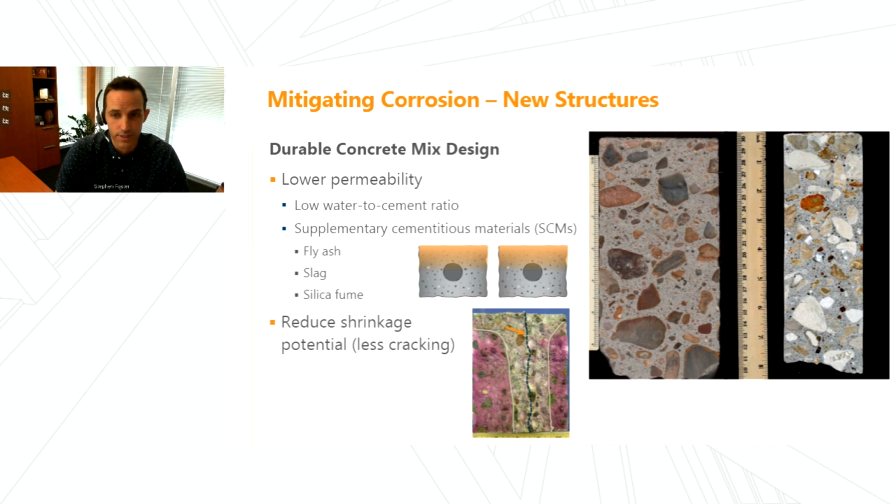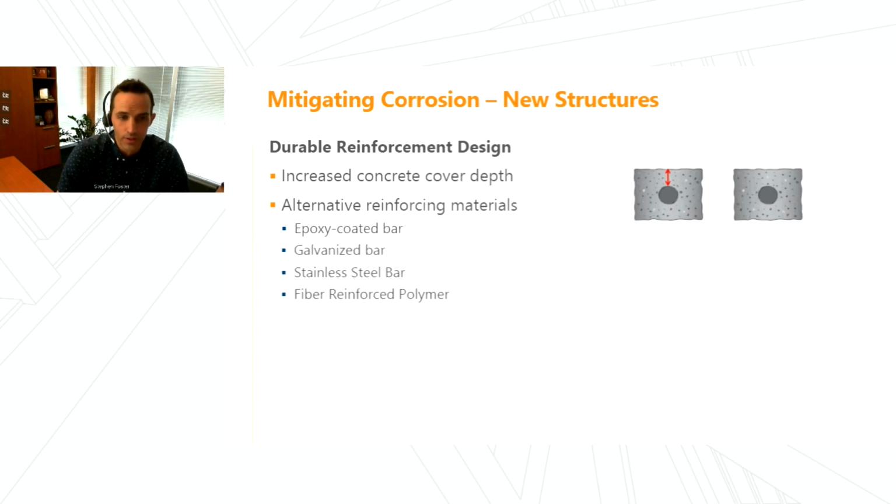In terms of reinforcing design for the actual rebar itself, there are things you can do to also improve the performance of the steel and the durability of the steel over time. And so first, you can increase the concrete cover depth. And so, the cover is just the depth of the reinforcing steel from the surface of the concrete. So for the same structure, perhaps you could increase the cover depth like you see here on the right. And now even for the same mix design, say the rate of penetration of those deleterious materials is the same. Well, now you've got a deeper cover, increased amount that material has to penetrate over time.